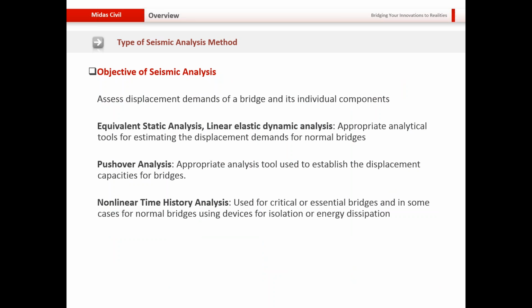We have different objectives for the different types of analysis. The equivalent static analysis or the linear elastic dynamic analysis is performed for estimating the displacement demand for the normal bridge. So we are going to perform the response spectrum analysis in order to obtain the displacement demand. After that, we are going to perform the pushover analysis in order to obtain the displacement capacity of the bridge.